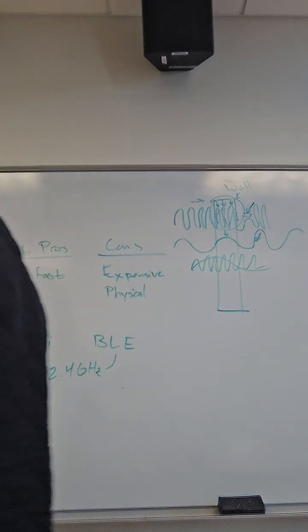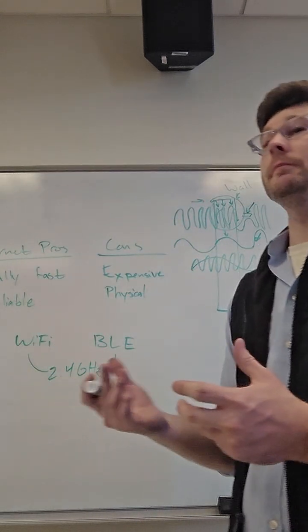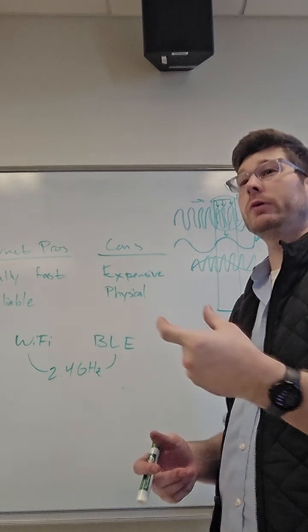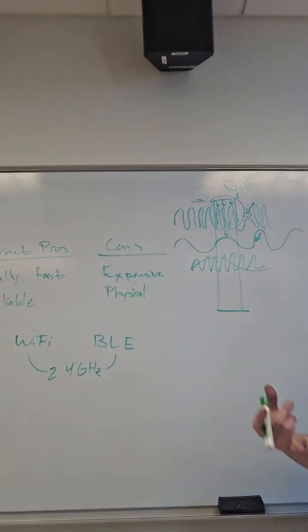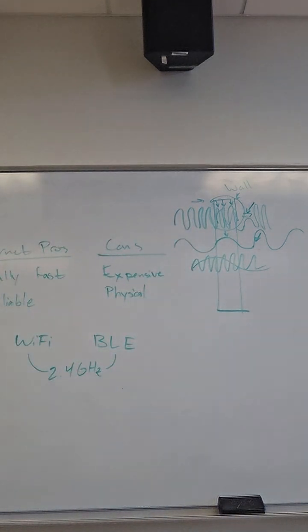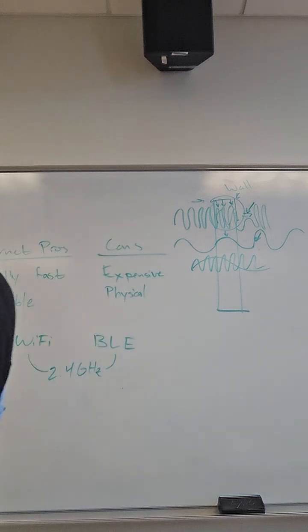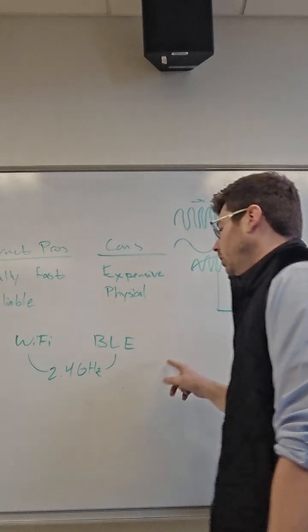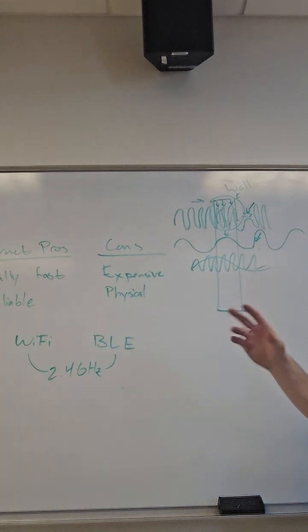So BLE beacons are something that are very common in industry. They are very small edge devices, sometimes as small as a coin or powered by a coin cell, and they would have very simple sensors on them. Again, like pressure sensors, temperature sensors, really low power stuff. And there would be many of them scattered, hundreds, thousands, through warehouses or through whatever, tracking the situation, the environment on the site. Okay, each of those devices alone can only talk BLE. They can only jump short distances one to the other. So they can't talk to the internet directly.